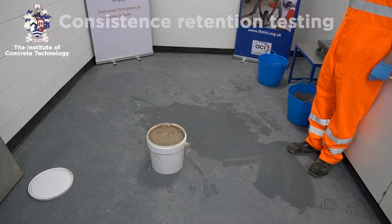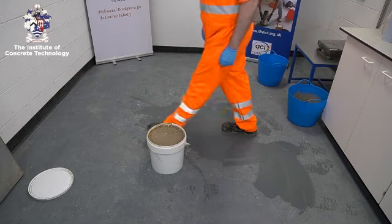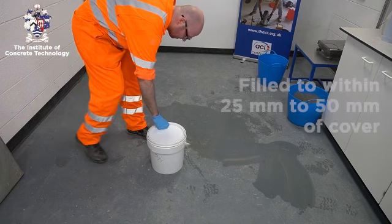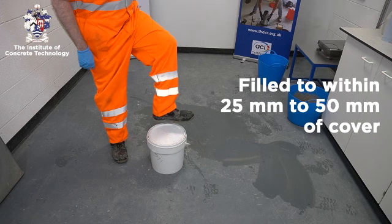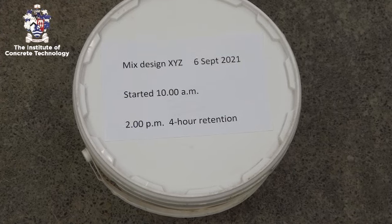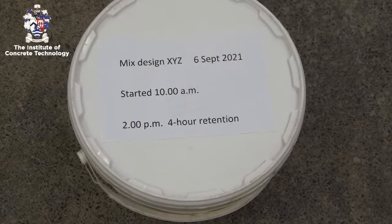Where the consistence retention of the concrete is required to be tested, the quantity of the concrete sampled shall be not less than 1.5 times the quantity estimated for the tests, but also sufficient to fill the sealed container to within 25 mm to 50 mm of the cover. The containers shall be stored at the location of the point of sampling from the discharge until required for testing.